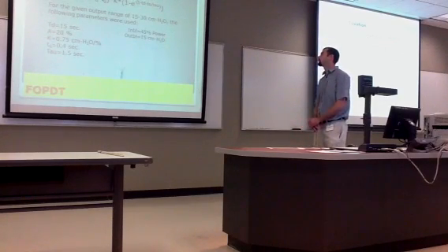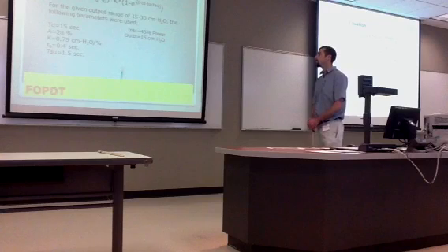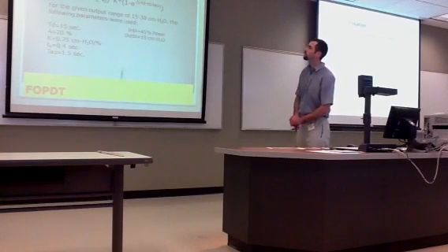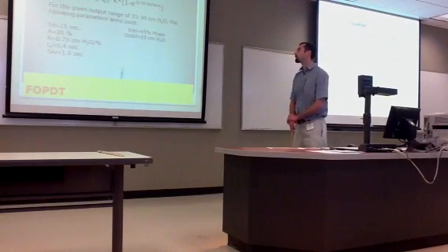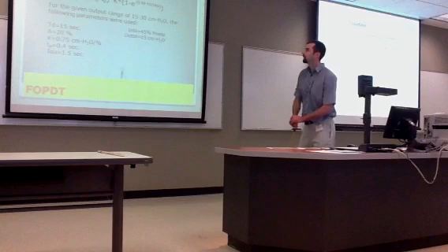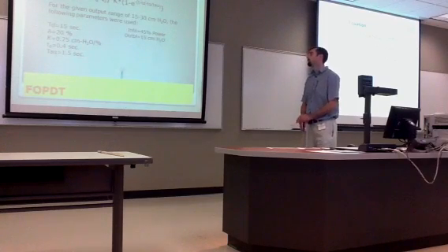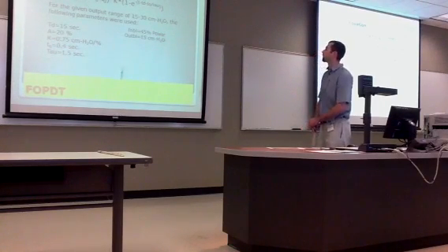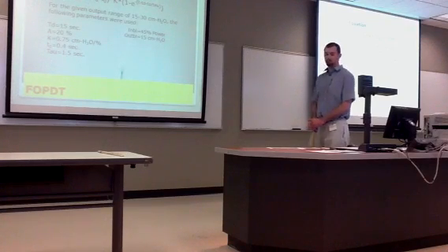Using that formula in a range of 15 to 30 centimeters of H2O, we were able to find the following parameters: TE being 15 seconds, A being 20%, and our K value of 0.75 centimeters of H2O per percent. T naught being 0.1 seconds, tau being 1.5 seconds. We used an input baseline of 45% power and an output baseline of 15 centimeters of H2O,